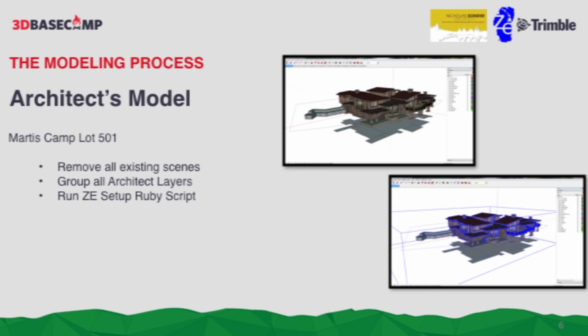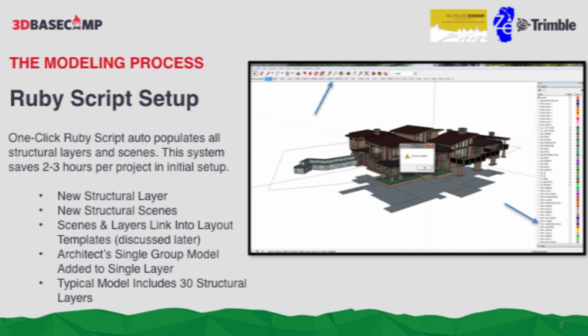And then Jesse here wrote our own Ruby script for Zachary Engineering that, when we run it, is going to go ahead and populate our entire model, everything we need. So with one click, all of our scenes are created. All of our layers are created. We basically start with STR, and then we go by level. We only need 10 layers per level. That's it. And so a 4-story is 40 layers. That's all we need to work with and create everything into LayOut.